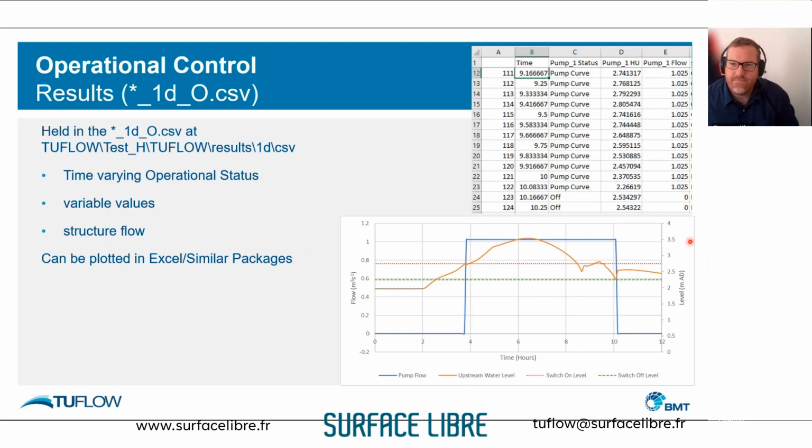How can we deal with velocities in the entrance, I guess, of the culverts with the connection with lines and polygons? Yeah, so if we are connecting to the 1D domain, there is a representation of the transfer of momentum, but it's not a full connection. It's not a full representation of momentum as you're going into a 1D structure. There have been some changes, I think in one of the later releases of 2020, where we do take into account approach velocities.